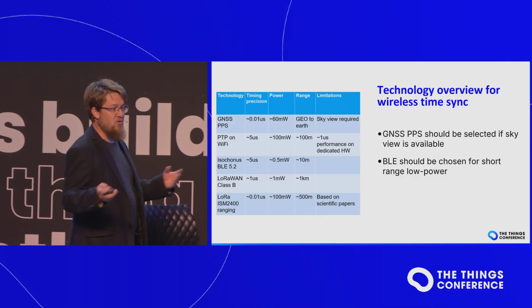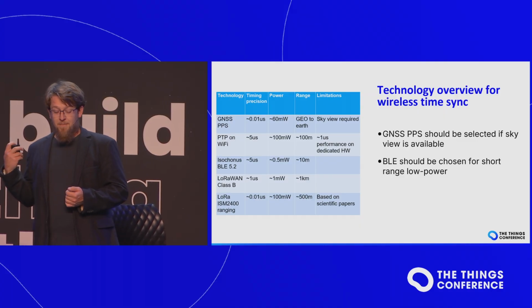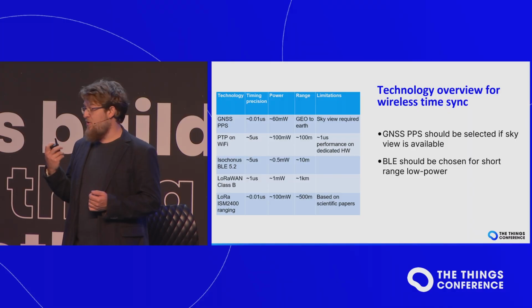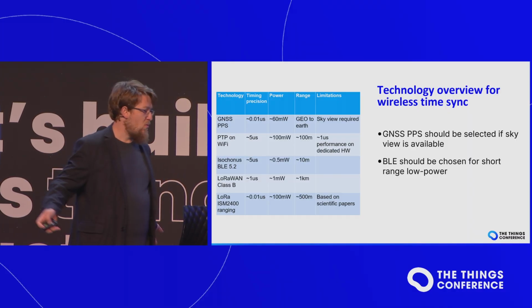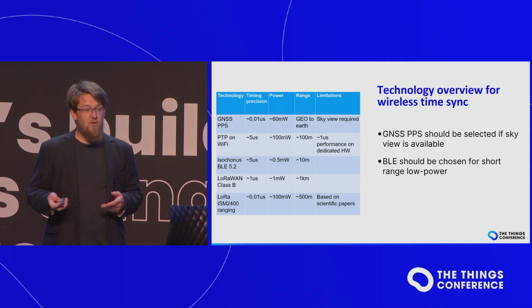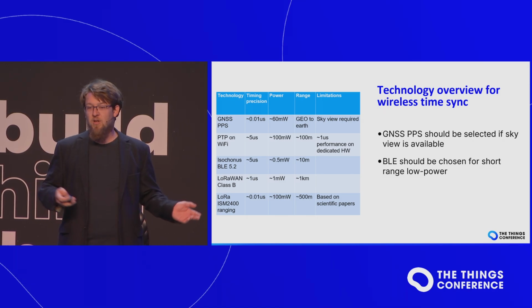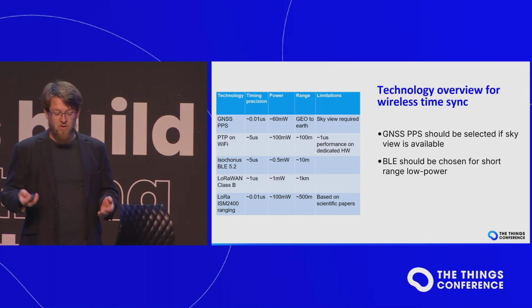Now, there are benefits and drawbacks to all of these technologies, generally in power and range. So, let's say you're doing a solution within a short range of a few meters, Bluetooth or Wi-Fi will be your go-to solution, because it's easy, you can send quite a lot of data, and usually you're OK with power.